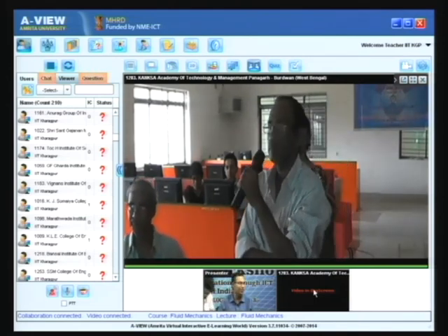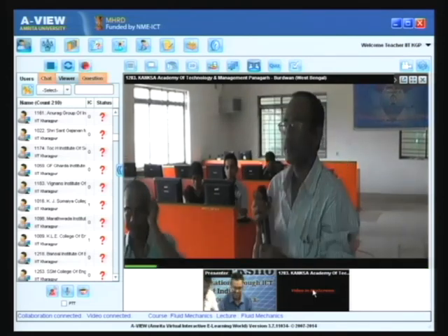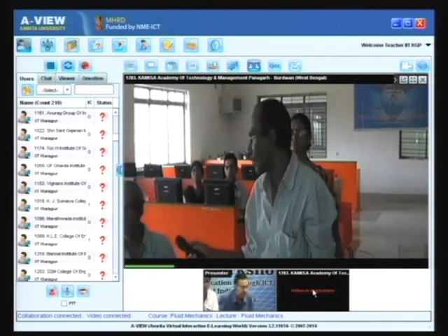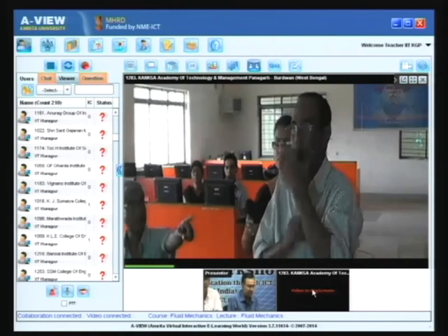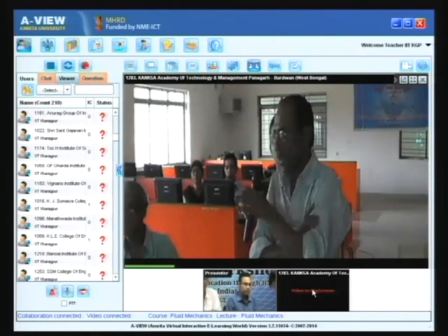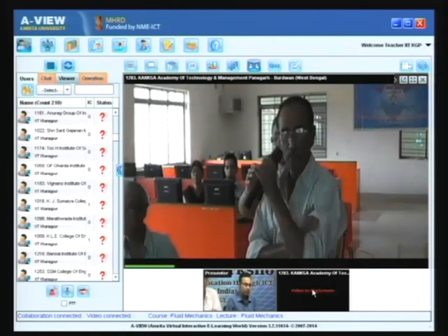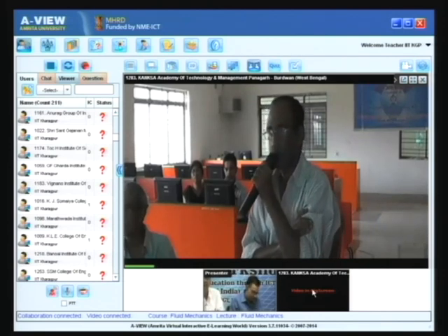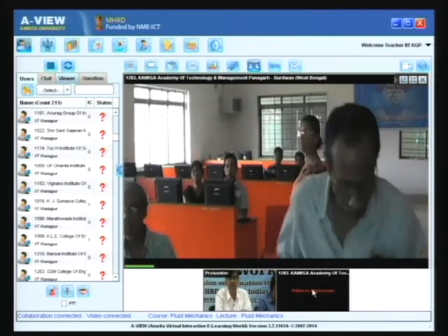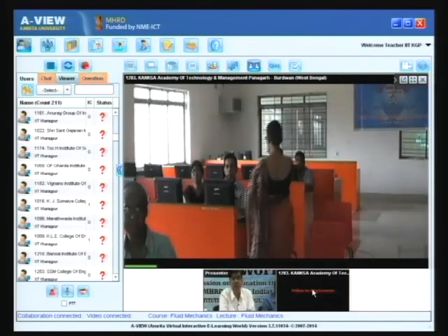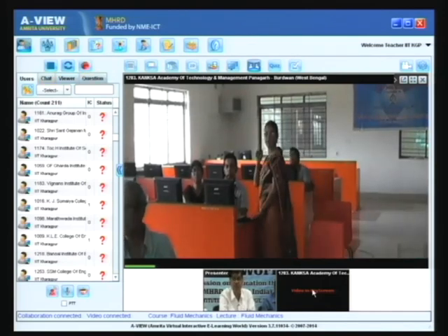Yes, please tell what you want to say. You see that V square by A square is the square of the Mach number. When the Mach number is below 0.33, try to understand, that means the velocity should be such that the Mach number is below 0.33. It is not the absolute velocity, but velocity relative to the sound speed. Then the density of the fluid may be taken as constant. So what do you want to know? Please tell.